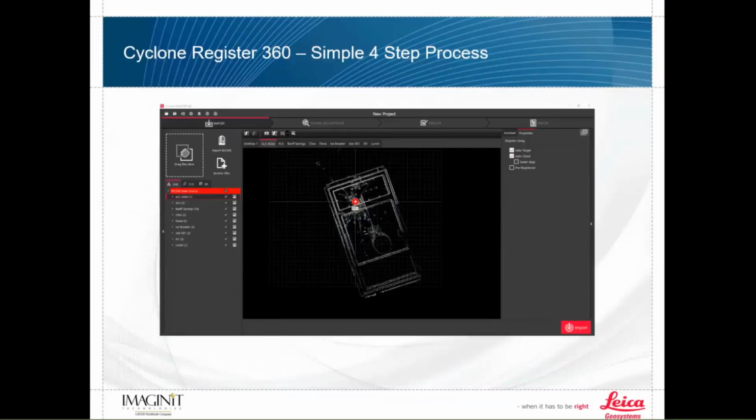So now we're going to jump into the software side of it. Basically, once I grab that RTC data, I drag and drop it in the upper left-hand corner. All I need to do now is start working with that data. So the registration, or the Register360, has really simplified and made this more of a workflow, like a flow chart. You'll notice at the top of the software, I basically have 4 tabs: import, review and optimize, finalize, report. That is our workflow process.